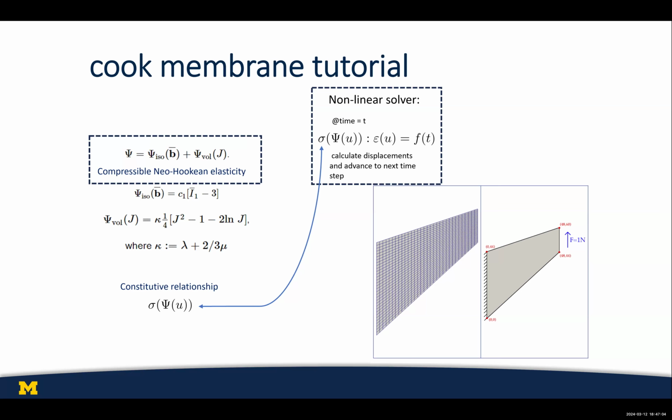Really, I just want you to know that there are some material properties that you would tune in that, and I'm going to show you how in deal 2, if you want to do a study changing this material property by small amounts, the way you do that is you make this parameter file, you parse that parameter file in deal 2, and then it's a C++ variable. So I'll just show you guys really briefly how that works.